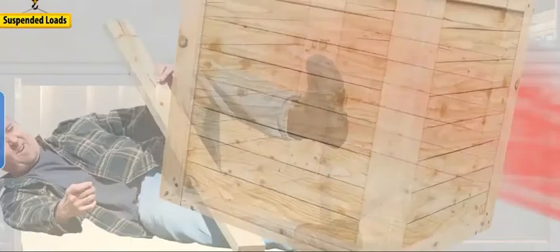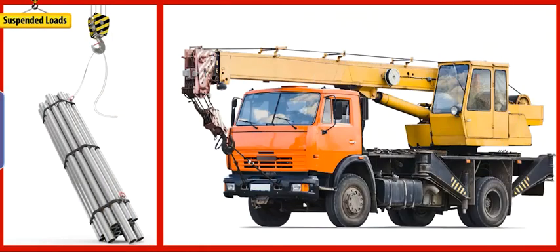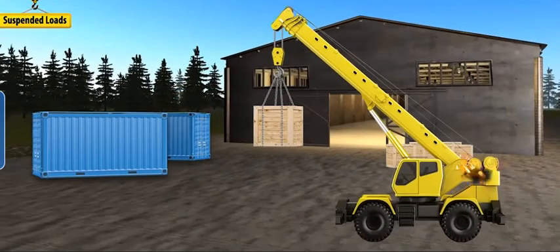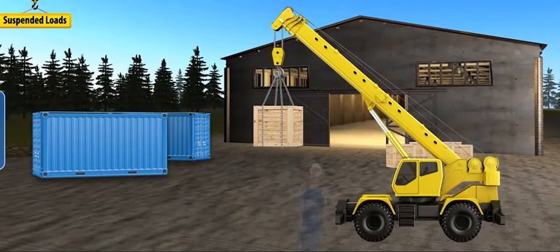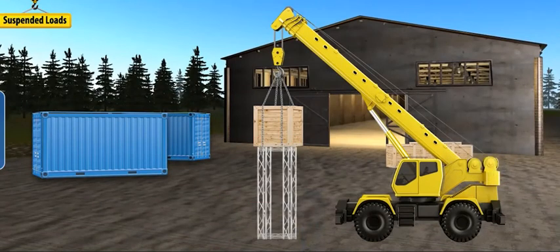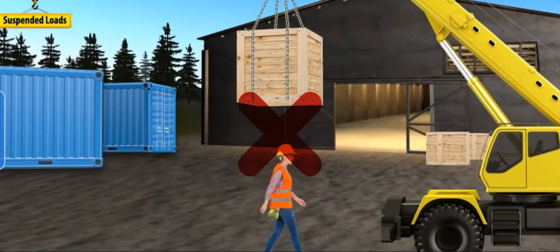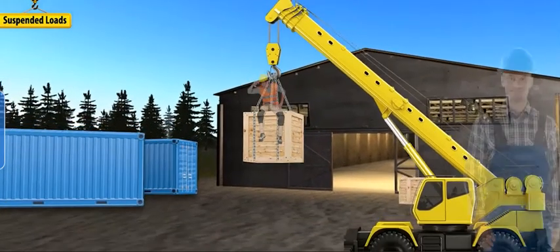The biggest danger when using a crane is crushing someone or being crushed yourself with a falling load or a piece of the crane. If you're operating the crane, never move a loaded crane over people for any reason. If the crane breaks down and the load can't be removed and gets suspended in midair, don't let anyone walk or work underneath the load unless it's secured in place, or some sort of support can be put underneath the load. Of course, you should never walk underneath a load yourself, whether it's moving or suspended, and never ride a suspended load. Never leave a suspended load unattended.